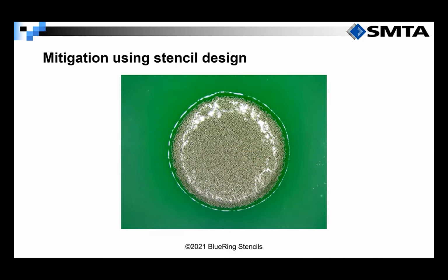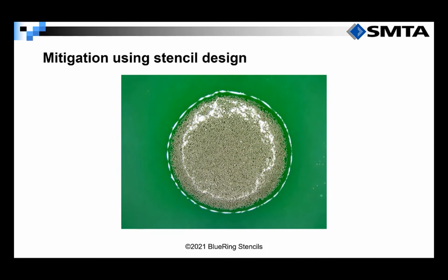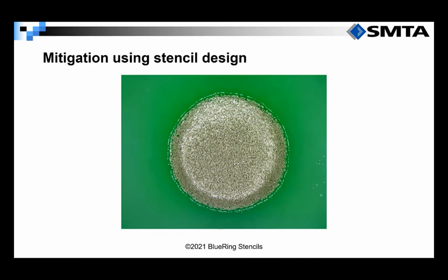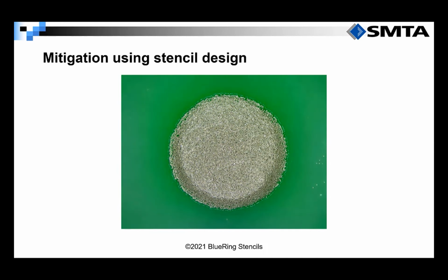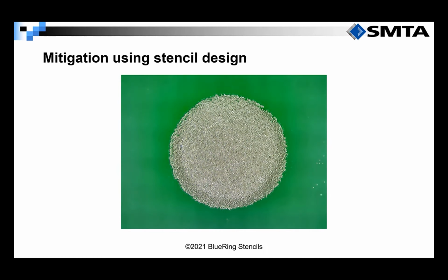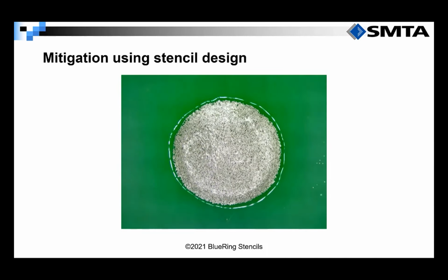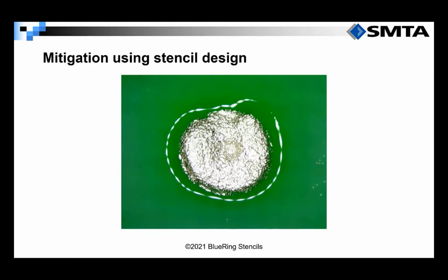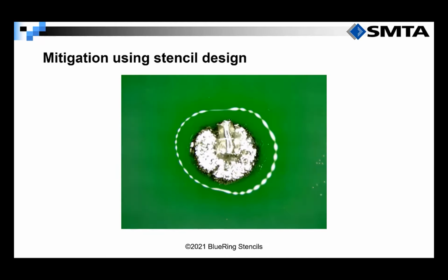So you can see here that the flux is activated during the initial reflow stages, and the solder spheres and the paste start pulling together. Then you can see the flux become active. The deposit almost looks drier. Then the solder becomes liquid and pulls in quickly to the copper land pad. Finally, you can see the outgassing and the volatiles burning off.